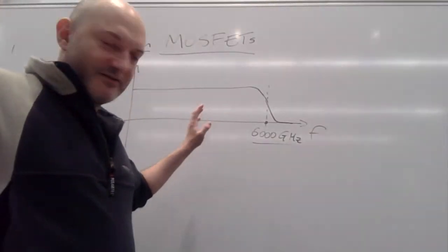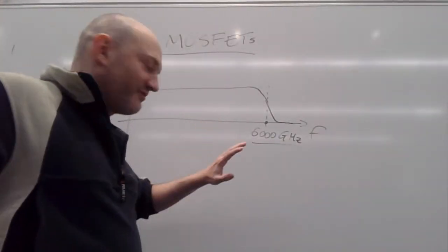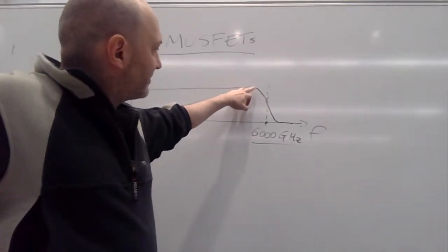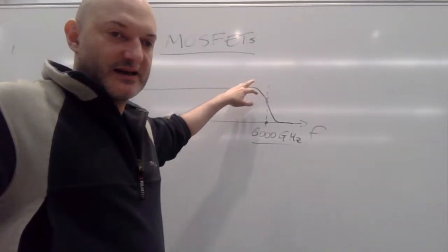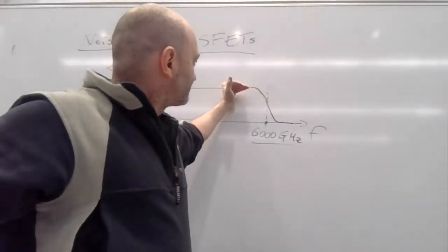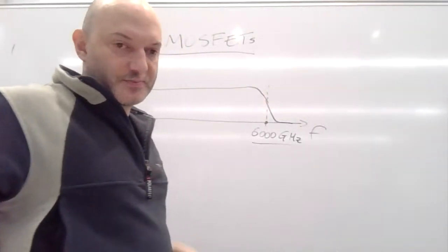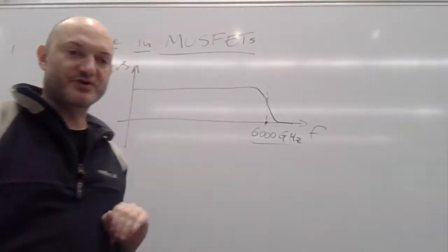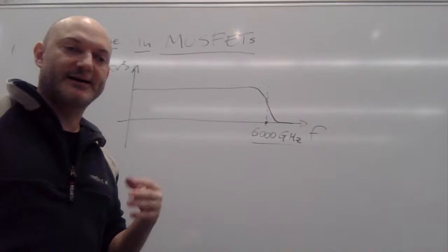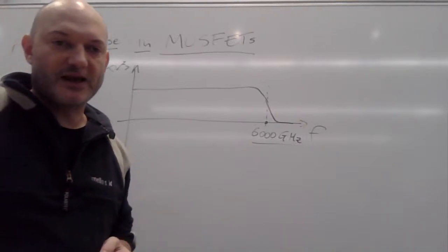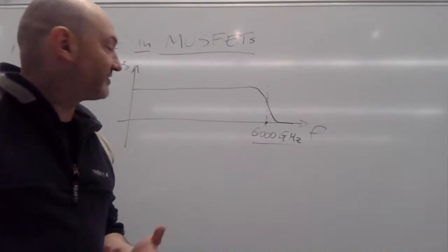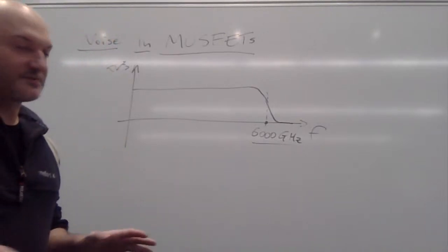So for normal operation of circuits, you're fine, so you don't have to worry about this drop. If you go up to 100 gigahertz, though, you need to be careful because this area starts drooping, so you need to account for it properly, okay? But the constant approximation, the white noise approximation, for any usable frequency in conventional circuits is absolutely fine, okay?